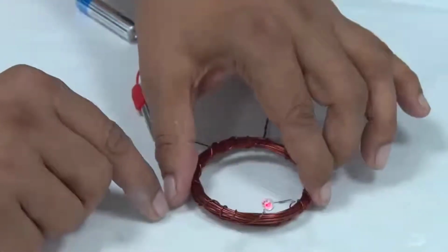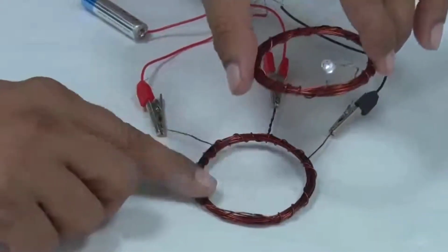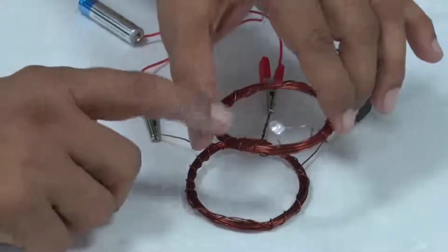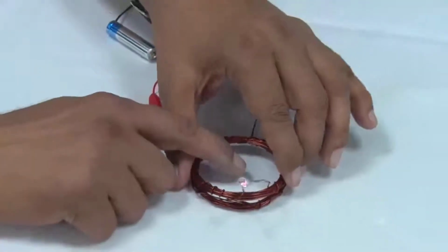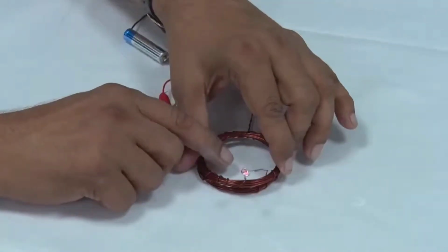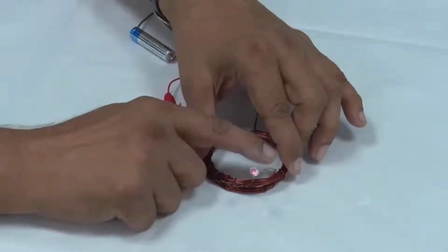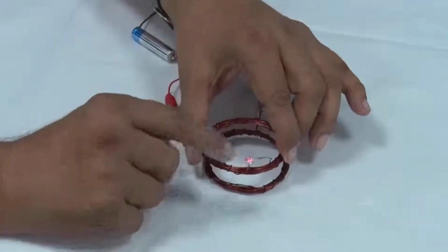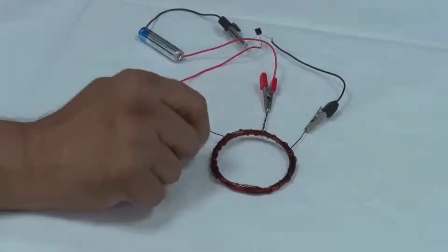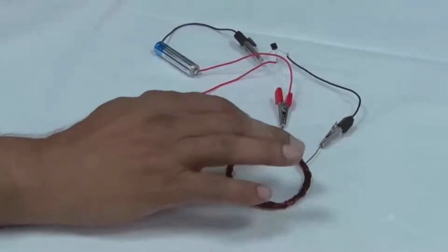You pass a time varying current here, and the time varying current produces a time varying magnetic field, and when you bring this other coil here, the time varying magnetic field gives you time varying magnetic flux, and the time varying magnetic flux creates an EMF, and that drives a current, and therefore it glows. So, that means you have a time varying current here, some kind of an alternating current here,